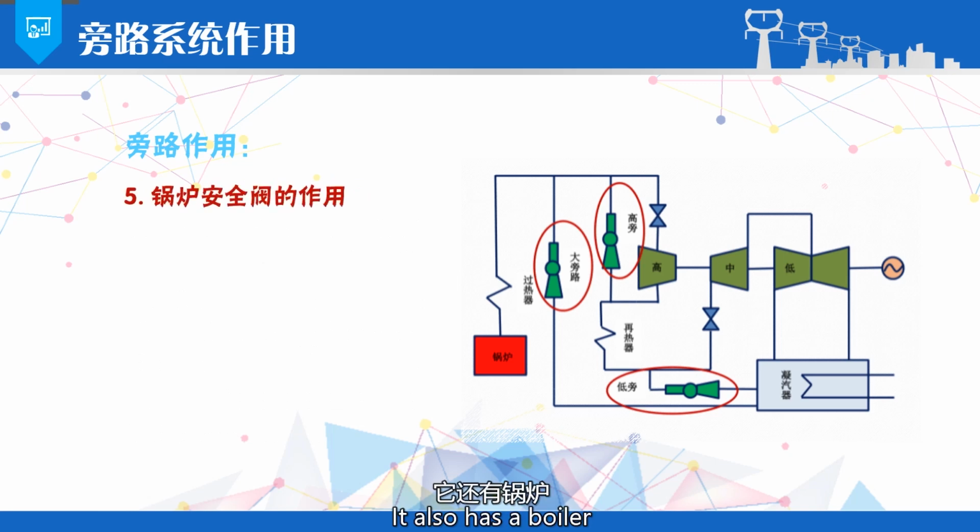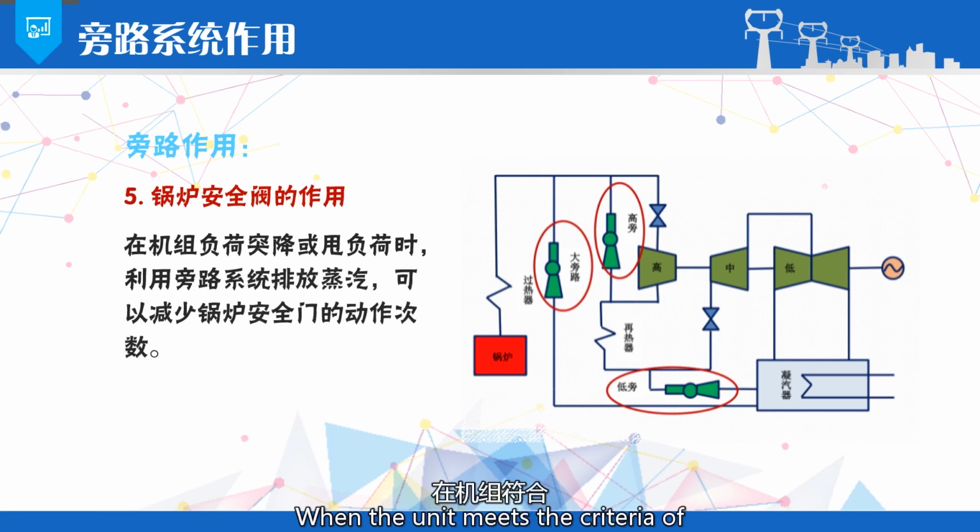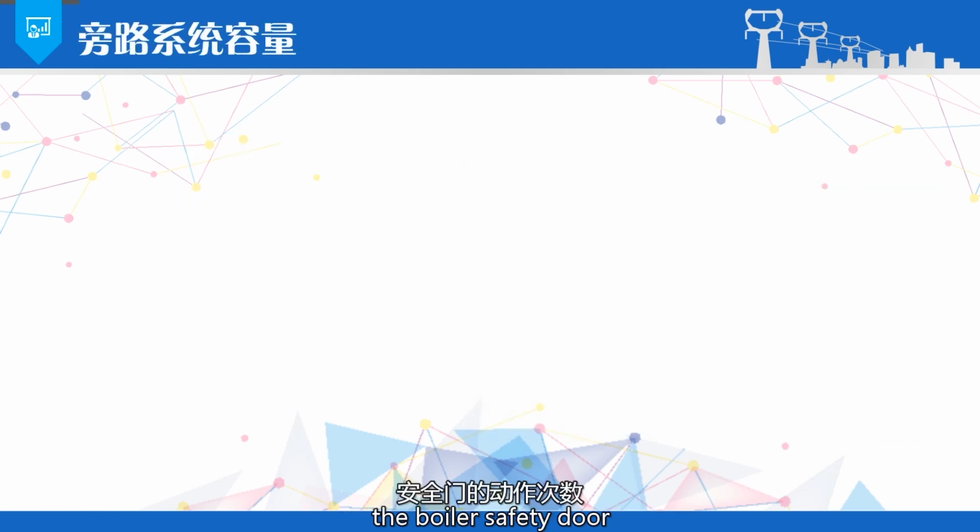It also has the function of a boiler safety valve. When the unit meets the criteria of a sudden drop or load shedding, using the bypass system to discharge steam can reduce the number of actions of the boiler safety valve.